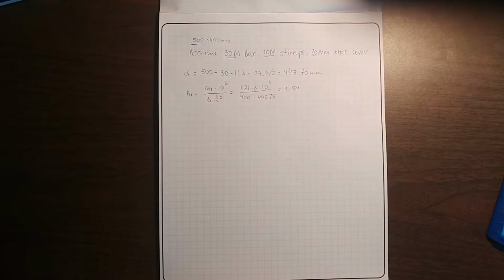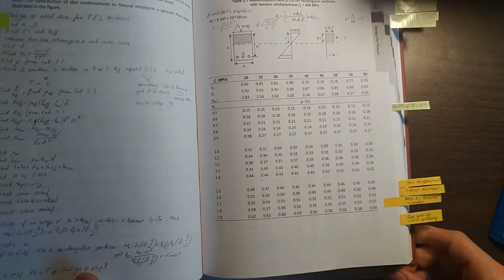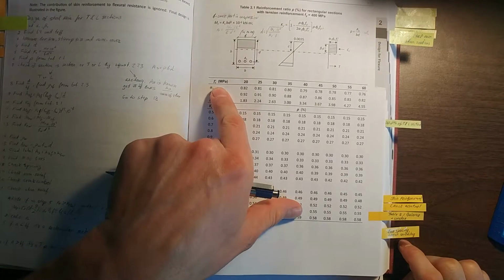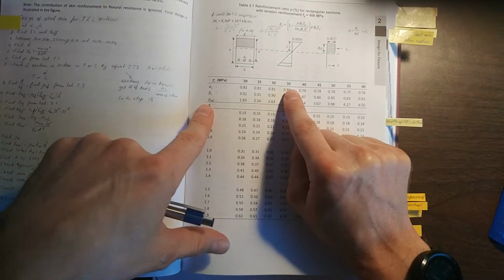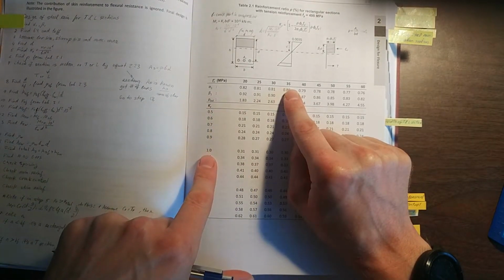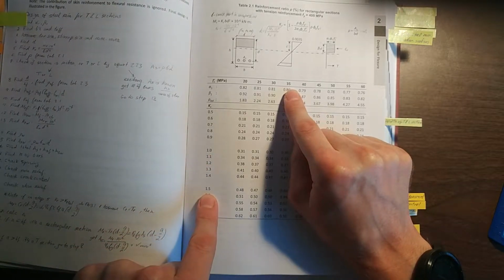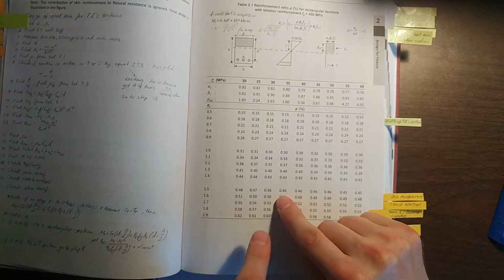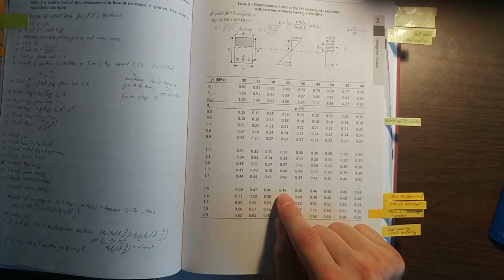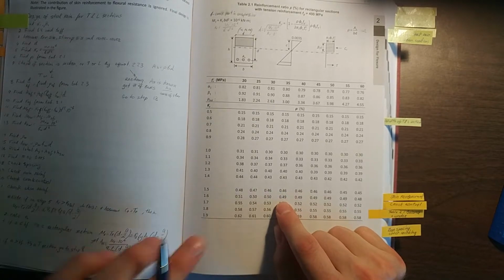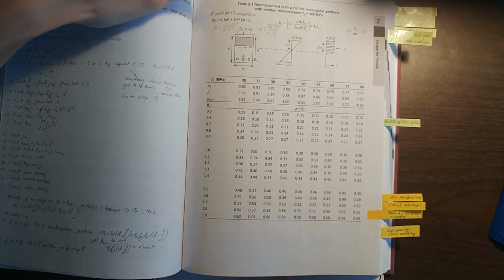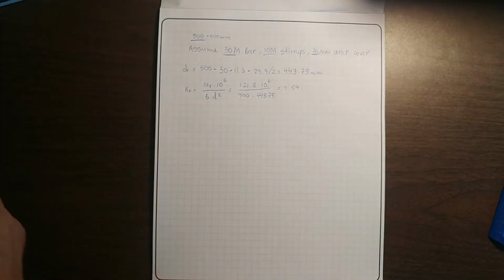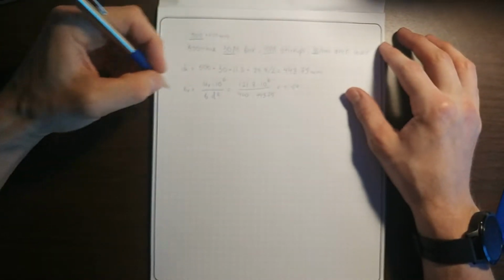And then we go to this book here, and we find the compression strength of concrete is 35, and then we have to find KR. So you see the KRs here, so you have to find 1.5. Then you go here and you get the ratio, the percentage of the steel reinforcement, 0.46, and then here for 1.6, you find the rho as 0.49, and you just have to interpolate between these two numbers. I'm going to show you how to do that real quick here.